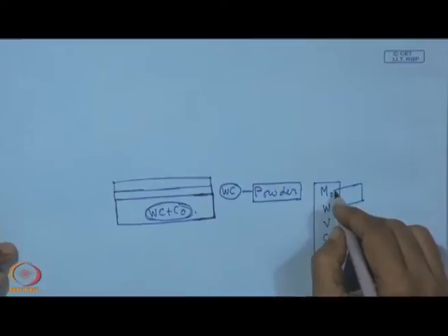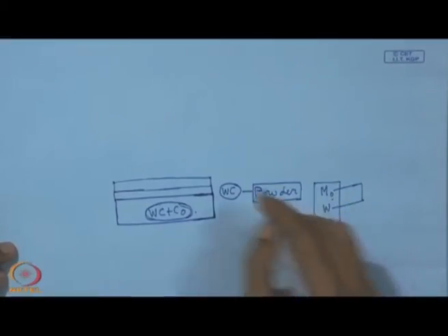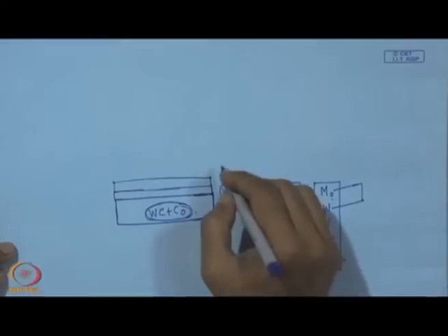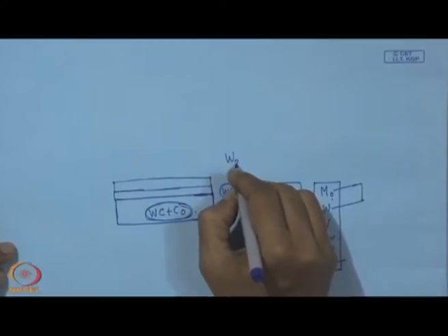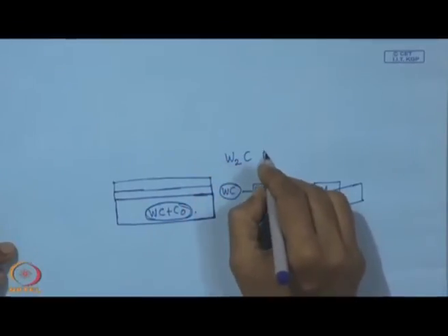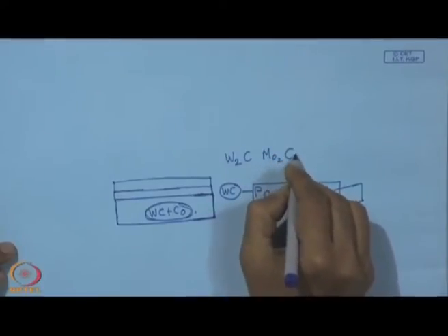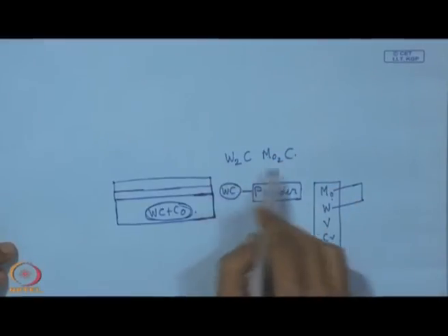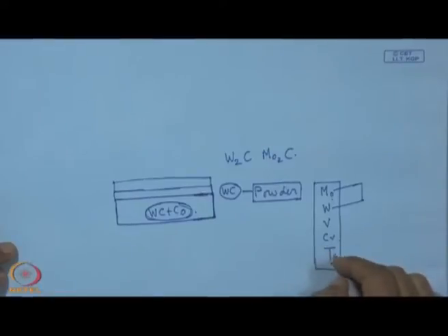Not only that, the density of nucleation on molybdenum and tungsten comes out to be very high, and this is because of some matching with the carbides of W2C and Mo2C type, which is not just possible with titanium or other materials.